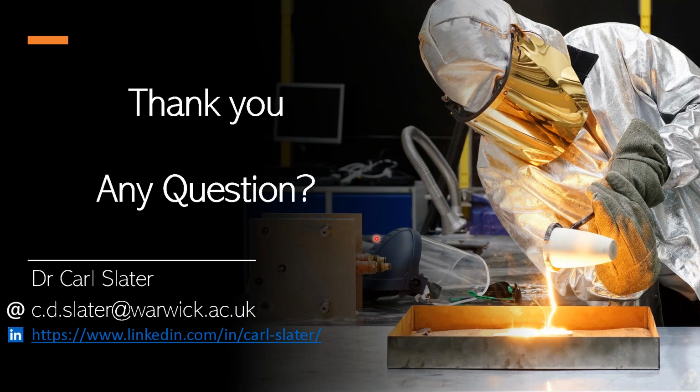We've got a very known microstructure to start off with. We heat it up, we hold it for different periods of time, we quench it, and we're able to look at the microstructure where the melt pool was. So what's the repeatability of that? What's the size of that with time and temperature, and how much control we have over it? So the size of the melt pool is entirely dictated by interrupted trials and in situ measurements. The thermal imaging camera is just nice for presentations.